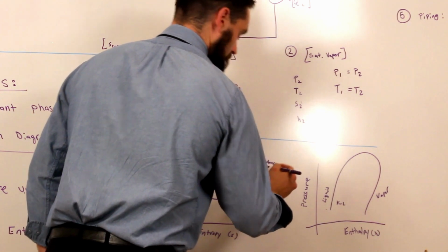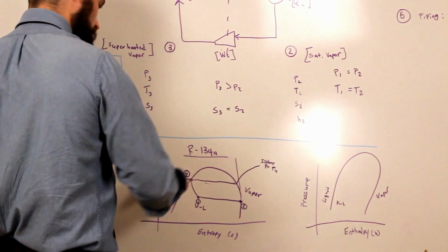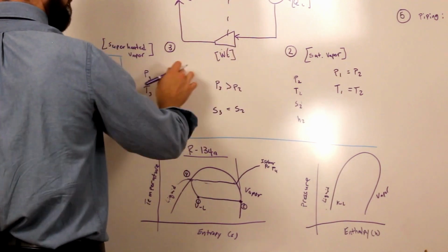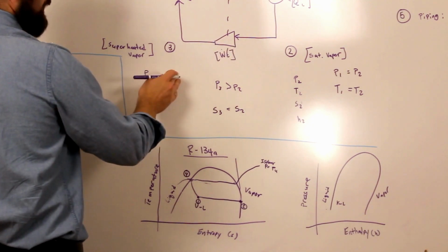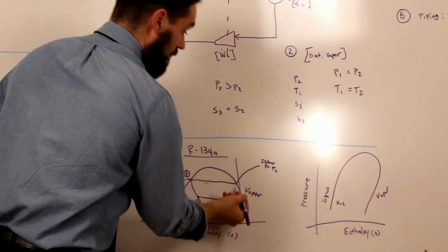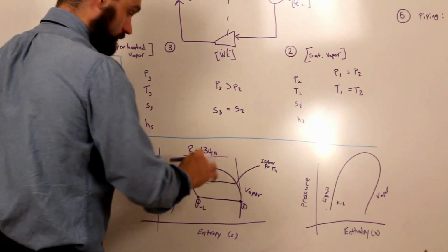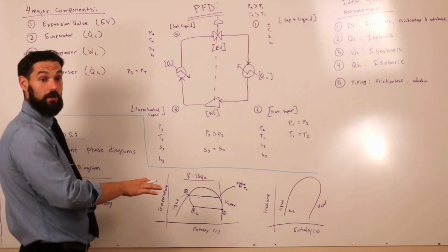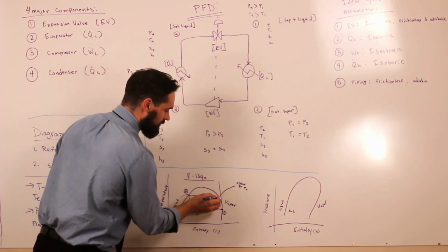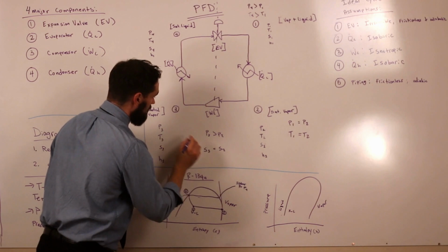So the pressure here is going to be pressure X, but we'll call it pressure 4. P equals P4. So this is the constant pressure line on this graph. So what's going to happen is we're going to increase the pressure coming across this compressor to the pressure that we desire based upon the design of our compressor. But we're going to stop at point 3, or pressure 3, which is also equal to pressure 4. So as we come isentropically, so straight vertical line, we're going to intersect with this pressure line here. Again, we'll have other ones that will be coming down on this graph. A lot of these graphs are very cluttered, so you have to know what you're looking at, and that's why understanding the general behavior of the lines helps, so you can know which line is what. Or we'd come up here until we find the pressure that equals our pressure 4. And this will be our state 3.